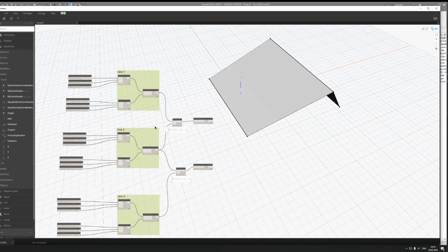They have a different way to create the loft surface, but they have the same logic. That's why I'm trying to keep this logic in Dynamo and Grasshopper. After this tutorial, you can open Grasshopper and just remember my tutorial. Okay, you should create the point by coordinates. You should create coordinates. And you will create this loft in Grasshopper too, because you will get the logic.